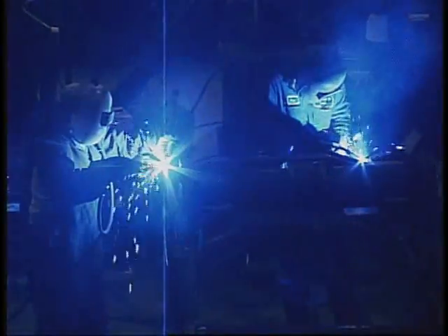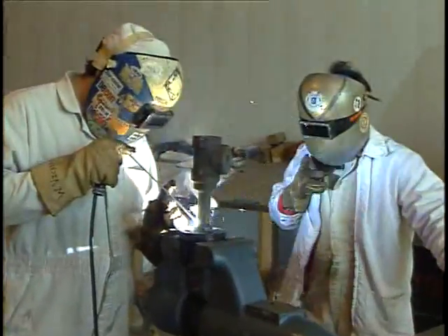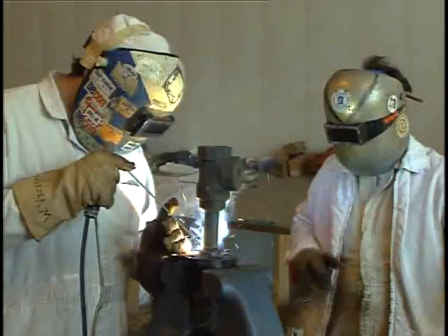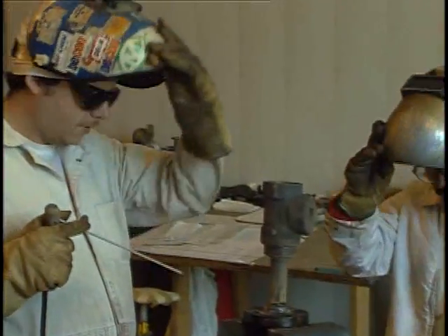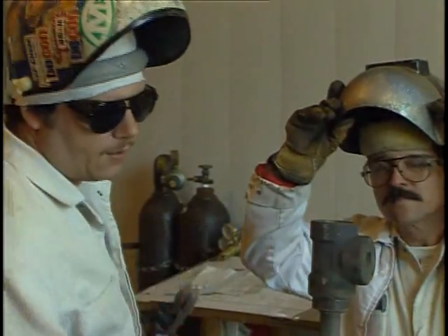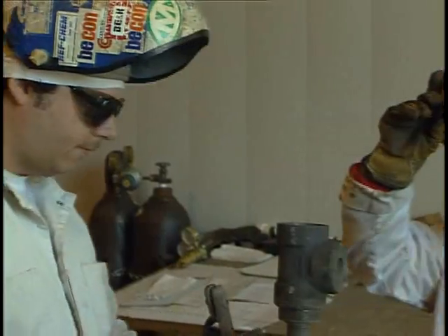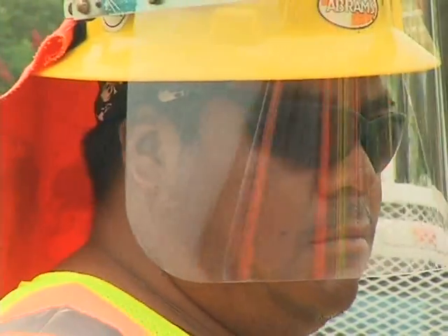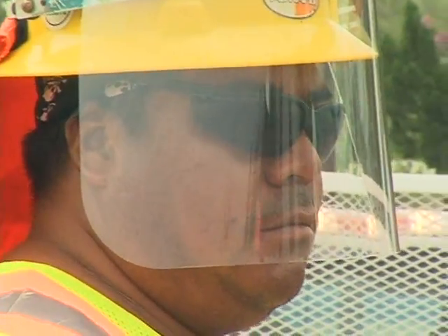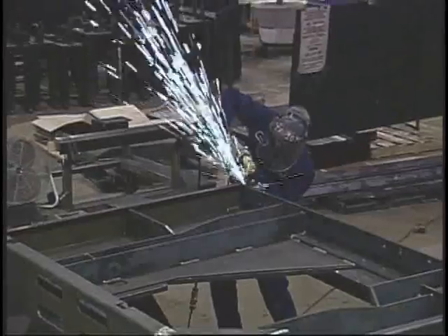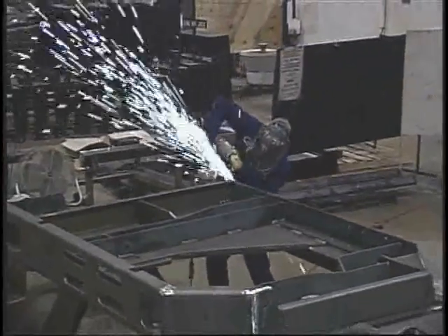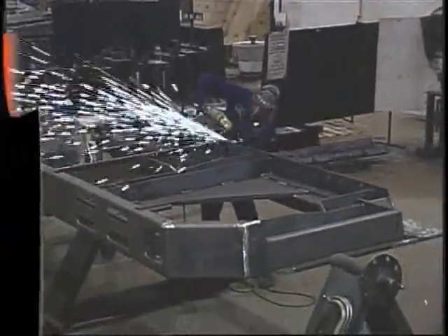Welding shields protect the eyes from burns caused by infrared or intense radiant light. The shield also protects the face and eyes from flying sparks, metal spatter, and slag chips produced during welding, brazing, soldering, and cutting. Face shields do not protect employees from hard impact hazards. However, hazardous liquids, nuisance dusts, and potential splashes are kept away from the face.